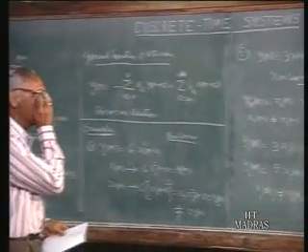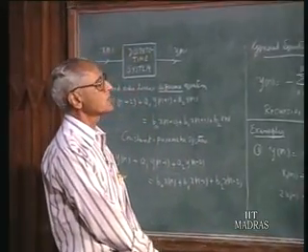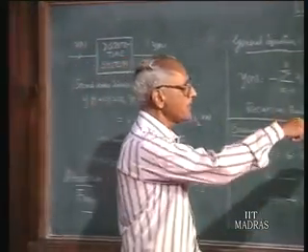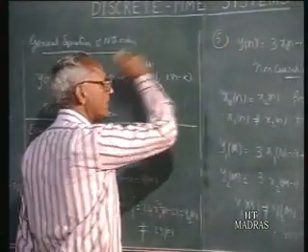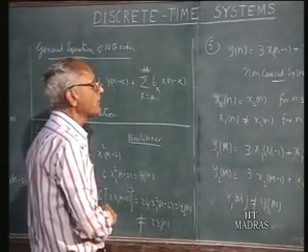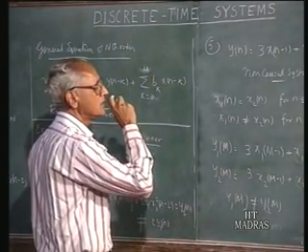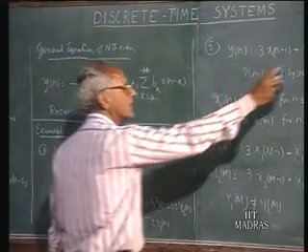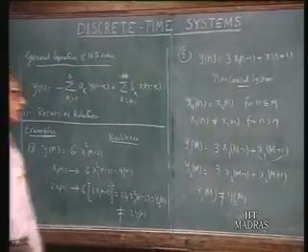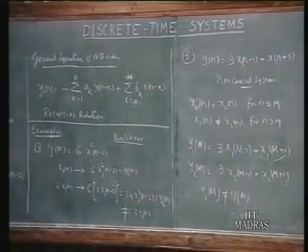The final conclusion from this is the argument: the highest argument associated with the dependent variable, whatever it is, the highest argument associated with the independent variable should not exceed that. Here n plus 1 is exceeding n, therefore, this is not a causal system.